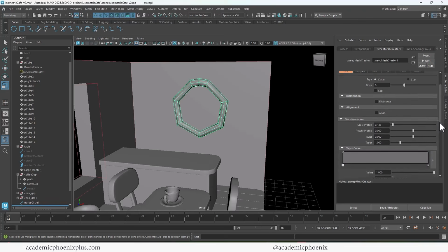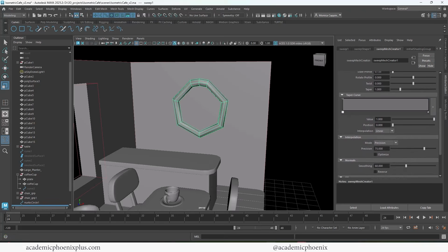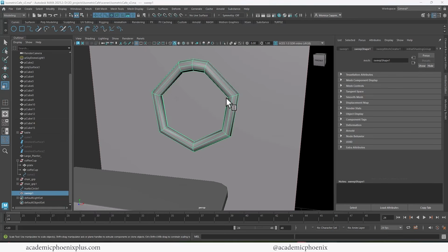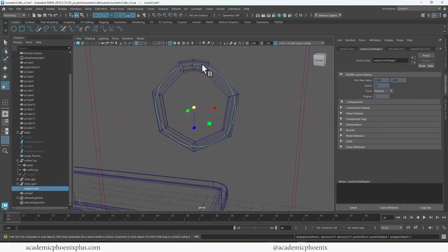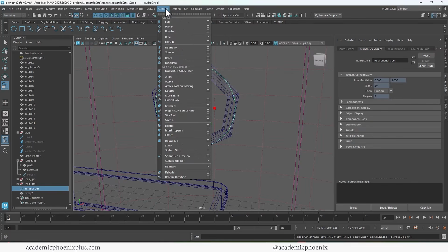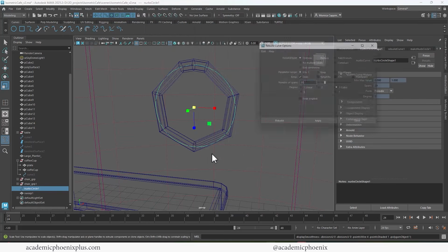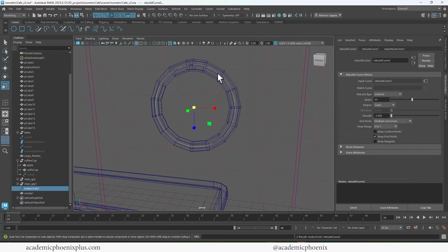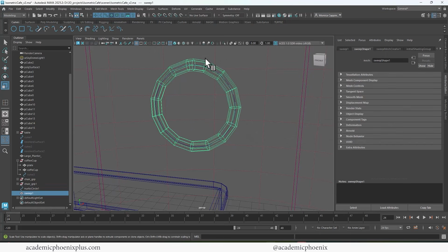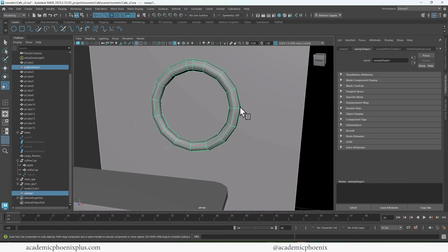And we don't need to rotate it or anything like that. As you can see, it's a little cubic, and if I press the number 3, it has a really funny shape. So let's grab the NURB circle. It's a little hard to see, so I'm going to turn on wireframe, and we're going to go to, again, rebuild options, and let's go ahead and crank it up to 45. And when we rebuild, you can see that it takes a lot of control vertices to get this nice curvature with the mesh, but it works, and that's the whole point. So let's go back to shaded on, and there we go. We now have a circle.